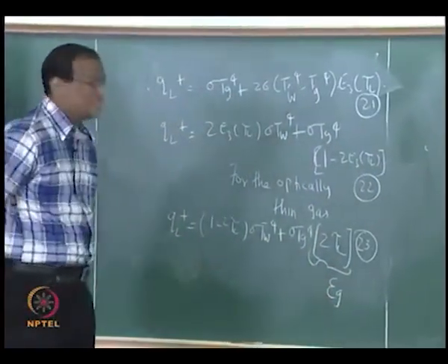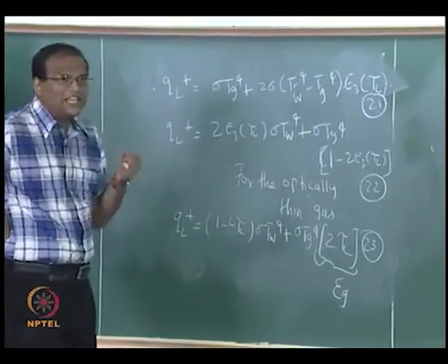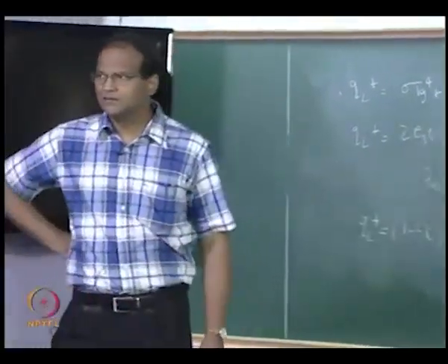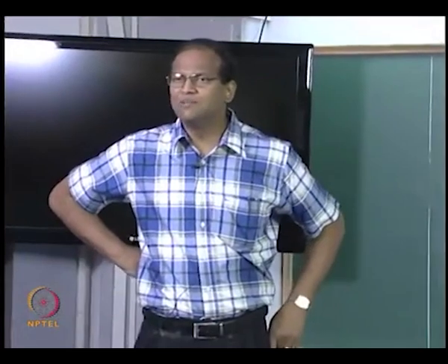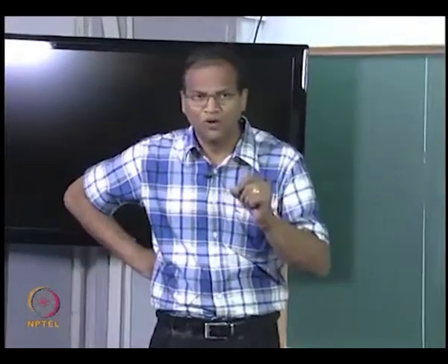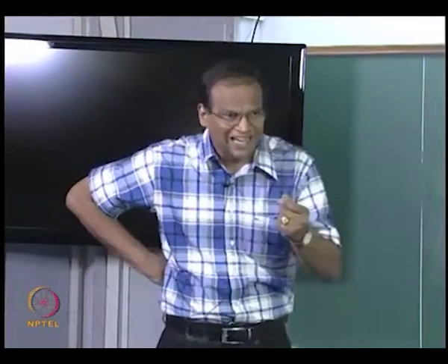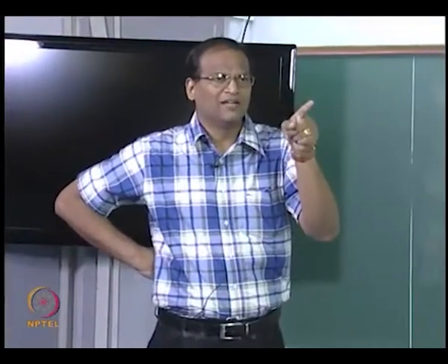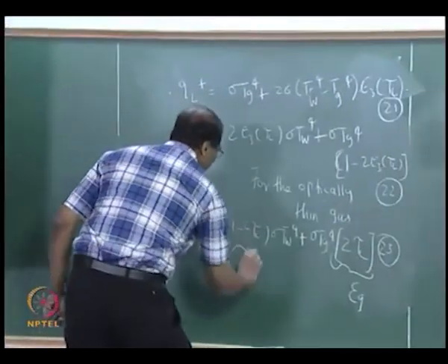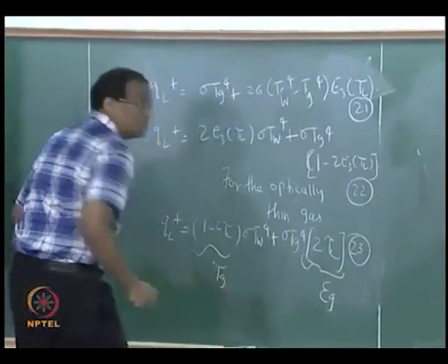If we say this tau L is an equivalent gas emissivity, then the second term is epsilon g sigma Tg to the power of 4. That is the radiation emitted by the gas arriving at the elemental area at x equal to L. The first can be treated as the transmissivity of the gas.